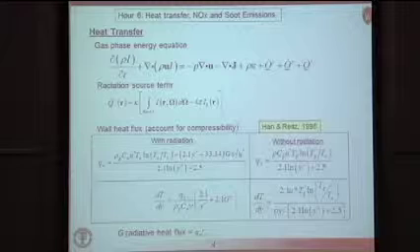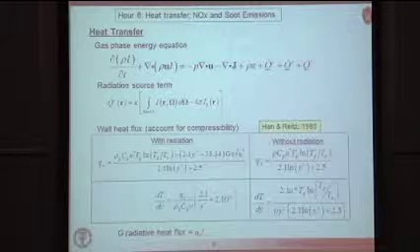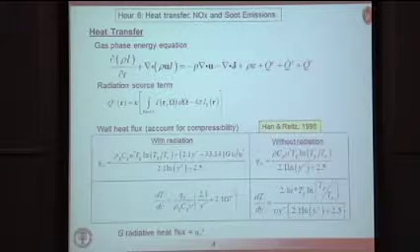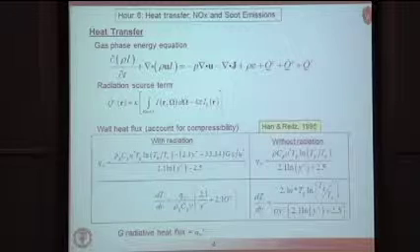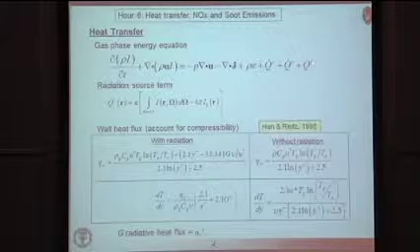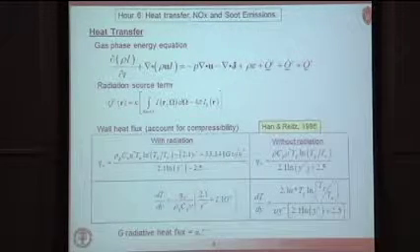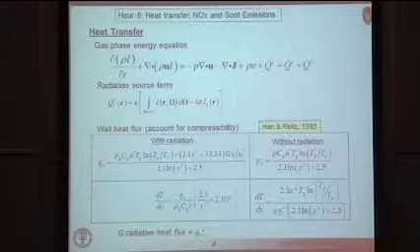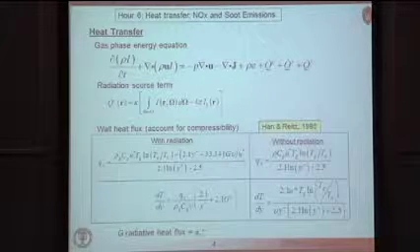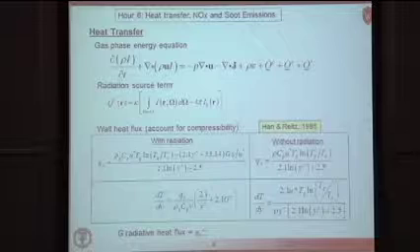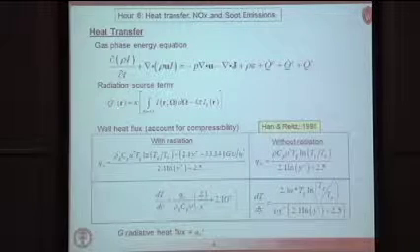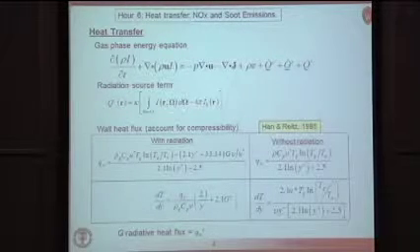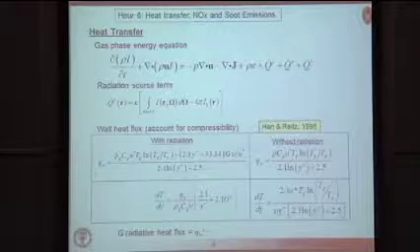Okay, so heat transfer. How does that come about? Well, if we go back to the energy equation, we've discussed all the terms here before, but I added a new term here, which is QR. So we can have radiation heat transfer, especially in a sooty engine where soot radiation is important. In order to do that, we have to solve essentially the radiation transfer equation.